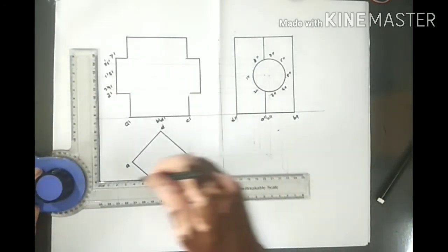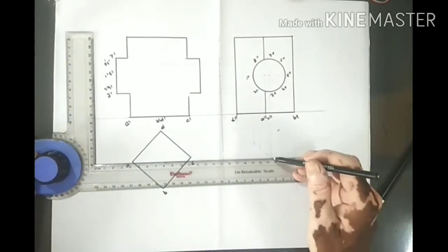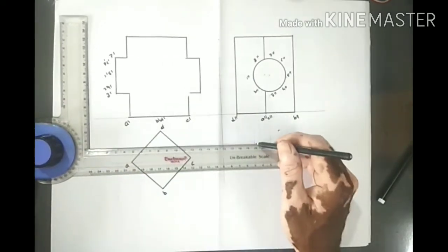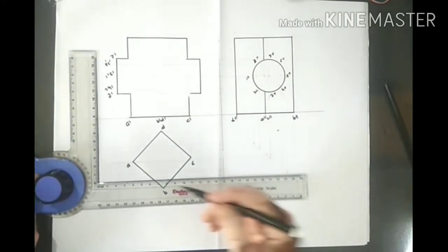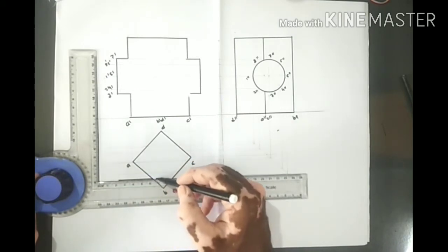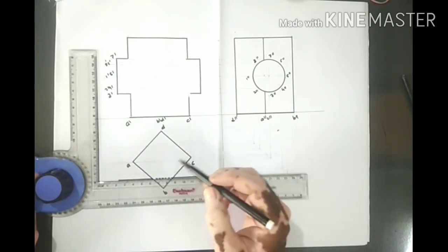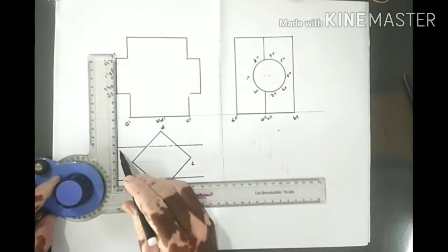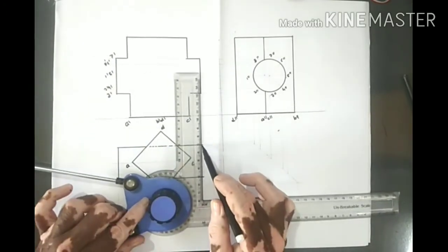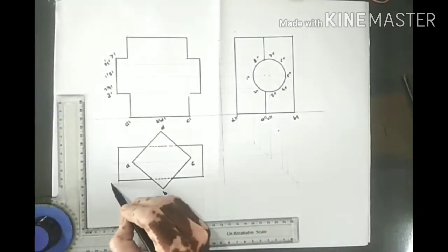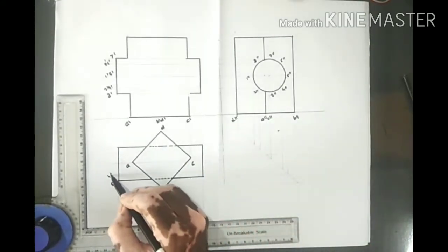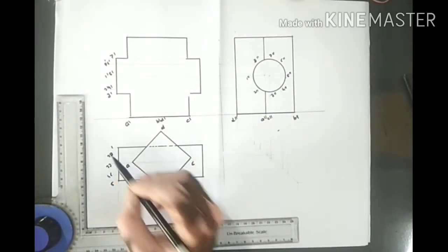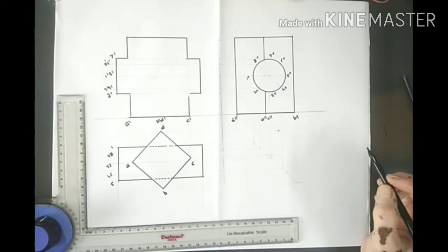So generators like this. So cylinder visible and then penetrate comes out, where the cylinder penetrates and comes out. So these are the generators. So this 5, this 4, 6, this 3, 7, this 2, 8 and this 1. Now locate the intersection points.